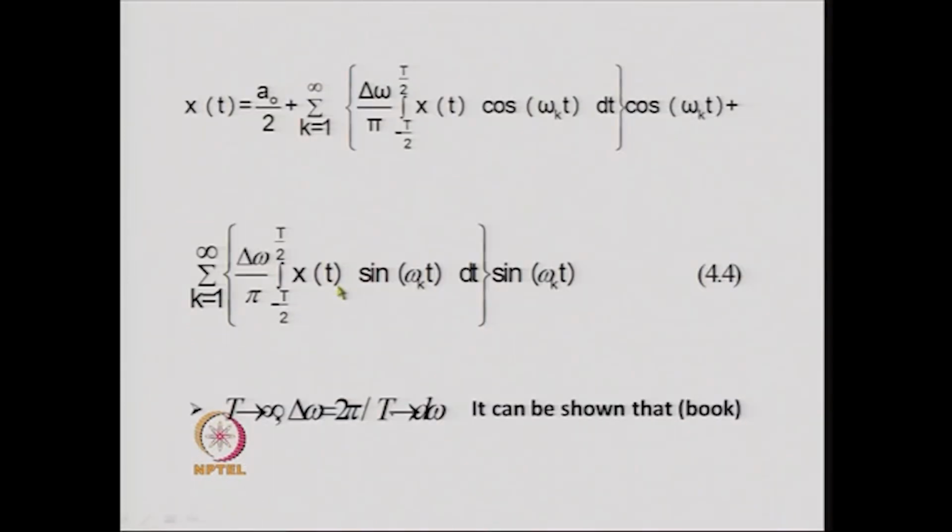In order to perform this numerical integration effectively, we now use FFT, that is fast Fourier transform, and in order to get back the time history of the signal, or time history of ground motion in this case, we can obtain it from the frequency components if we use IFFT.